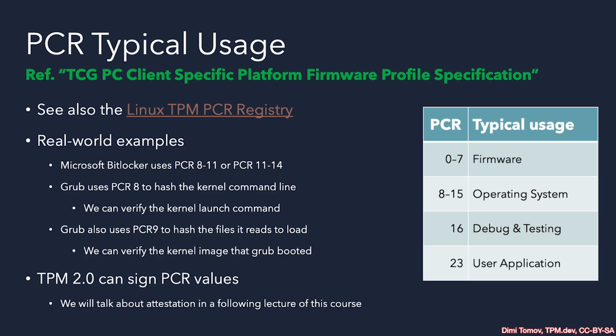This all adds up when we start using the TPM 2.0 to generate signed proofs as evidence of the state of the system. This is usually done using the TPM2 quote command to sign PCR values.